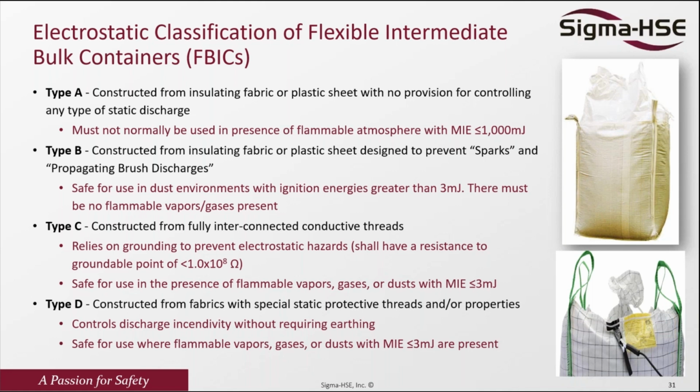Type B, somebody will say, is cheap and it's good. However, there's a real trick, and I think last week I visited a facility. They were using type C. I was happy. I clapped for them. But getting close to the equipment, I noticed that they missed the point. Type C is constructed from fully interconnected conductive thread. As you can see in the picture at the bottom, you can see this black thing there. That's the conductive thread, and this actually needs to be bonded and grounded. So you could have type C, and everything will be okay, but if you don't ground it, you are missing the point.